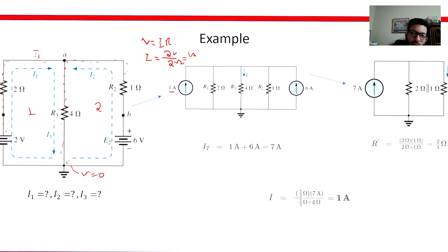So this is pretty simple because we can have a set of resistors in parallel, such as in this case, where the current is going to add up. Remember that the current in series is the same, but in parallel is different. So since this current source is in parallel with this current source, we can have a total current of 6 plus 1, 7 amps.